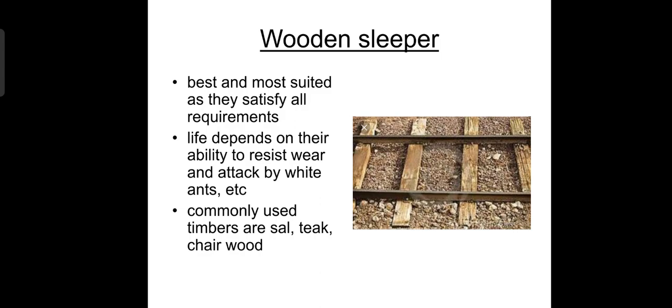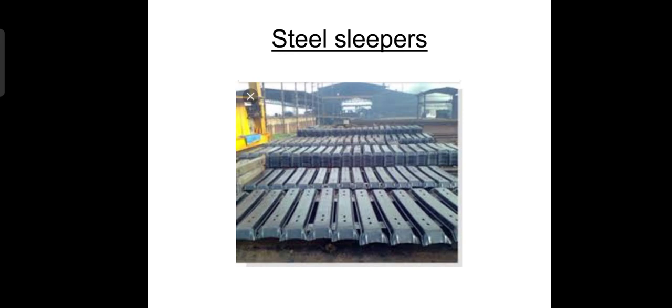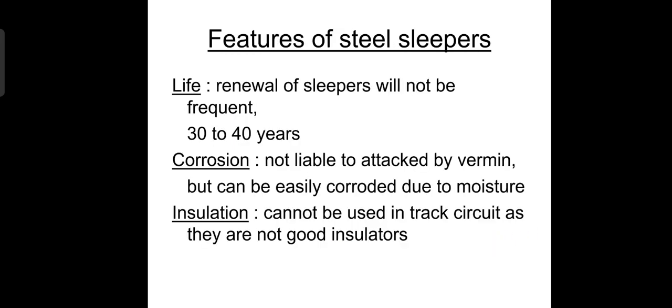Wooden sleepers. It is the best and most suited as they satisfy all the requirements. Life depends on their ability to resist wear and attack by white ants. Commonly used timbers are sal, teak and deodar. Steel sleepers. Features of steel sleepers: its life is about 30 to 40 years, so renewal of sleepers will not be frequent. Corrosion: not liable to attack by vermin but can be easily corroded due to moisture. Insulation: cannot be used in track circuit as they are not good insulators.